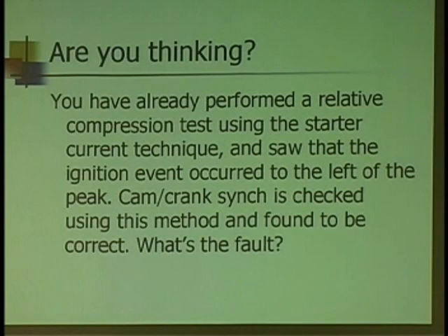Okay, see what I'm saying? Number one, it's a thinking man's game. That was a good thought. But you took two tests with your scope and found out why this car was running kind of ragged and didn't have any code set. What would the scan tool tell you? Cam sensor sync? Yes. Right?